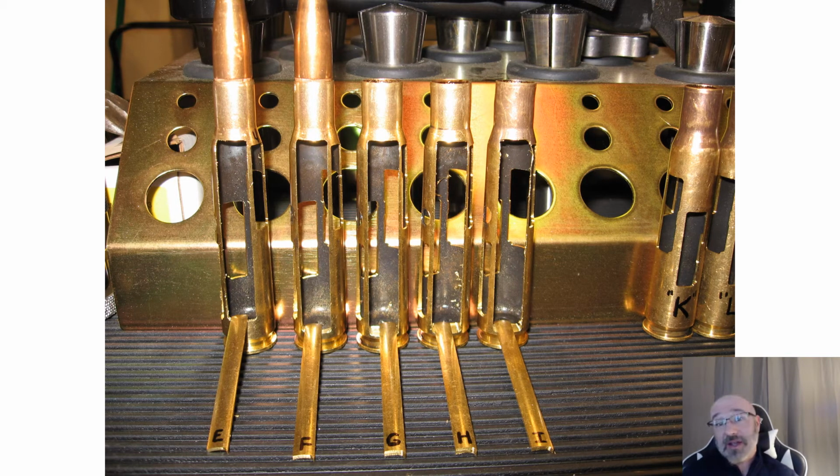As you can see, these cases are very small for these 50 cal cases. So we needed to order in some special machining bits and figure out special mounts and how we were going to clamp these down in order to do the machining and support them, because as we machined out a couple of pieces, they became less rigid and less durable, and would start to bend and twist on us while we were machining. So even within the machining process, there was a lot of designing that had to go on on the fly to really figure out how we were going to physically get the test specimens out of these.